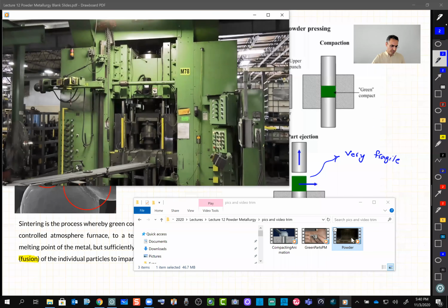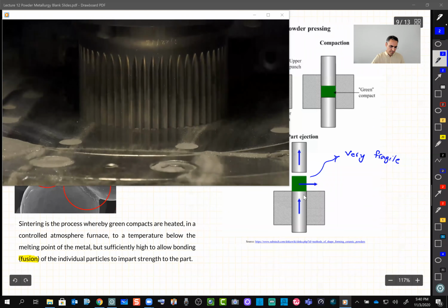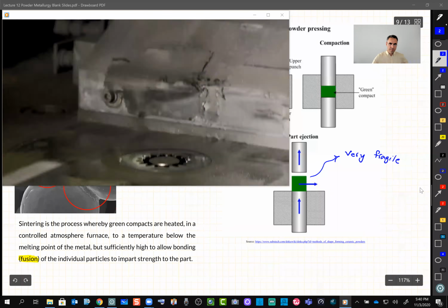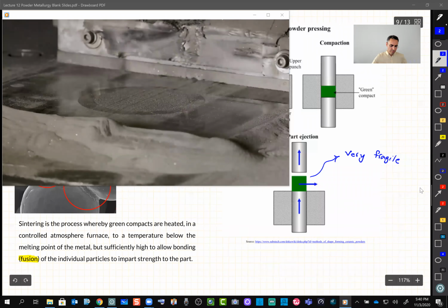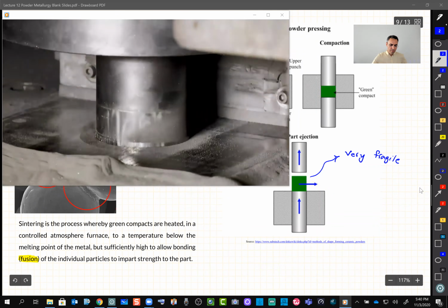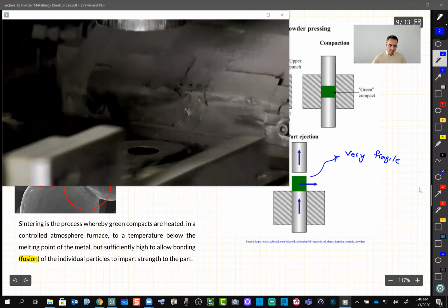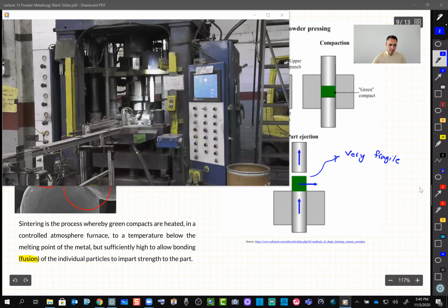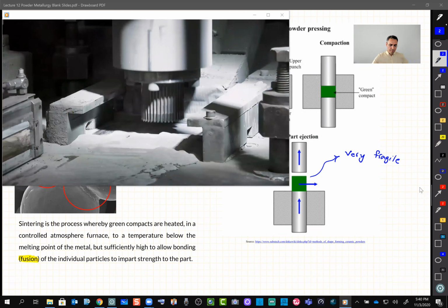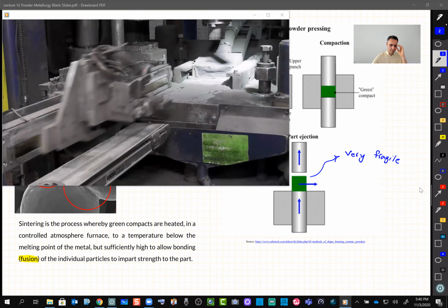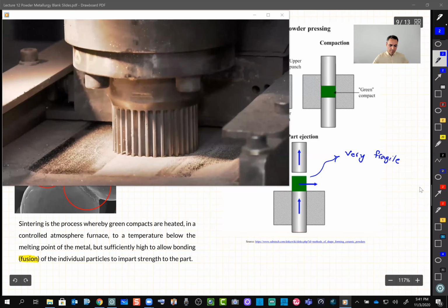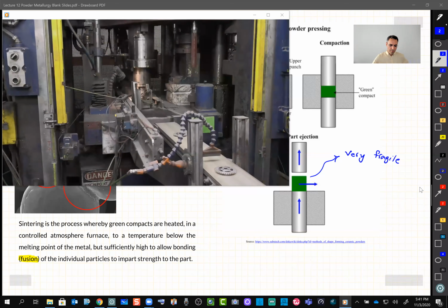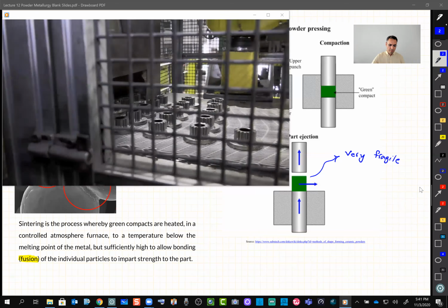That mixture is put into a compaction press. We compact the shape into what's called a green part, and that will have a pretty low strength. Certainly enough to handle, but I always say it's like the strength of an aspirin tablet. If you try hard, you can break an aspirin tablet. The structural properties, the end properties that you're looking for from the product, are not going to be in that green part, but it begins with the shape. So the PM process is kind of unique. You get a shape first, and then you get the properties. The properties are all developed in that sintering furnace.